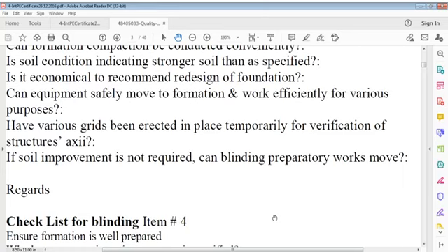Because existing soil is consolidated. Don't forget, it may be rock. It has a natural strength, and there is no meaning in disturbing the consolidated portion. It's not very common, but in case unexpected strata is available, you should use that rather than excavate for nothing. And if the building foundation is stable, in that case we can propose to raise some foundations to some level higher than was expected or planned.